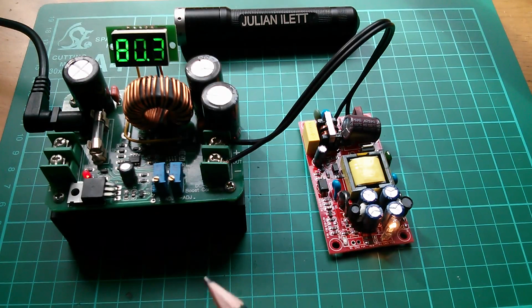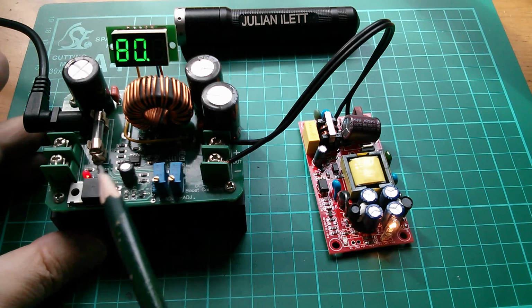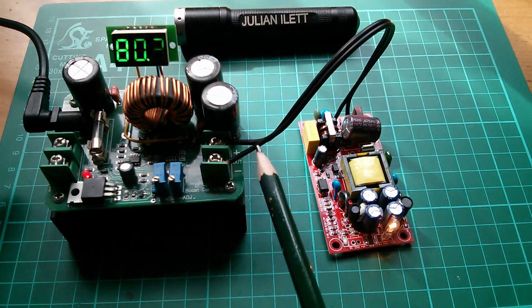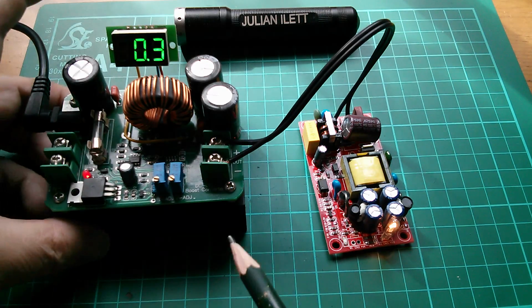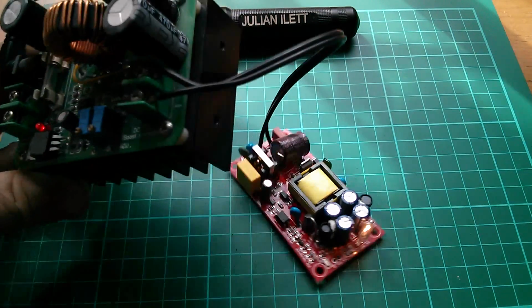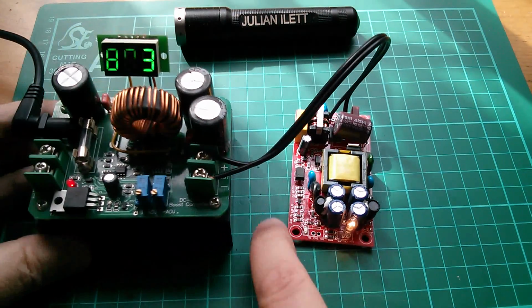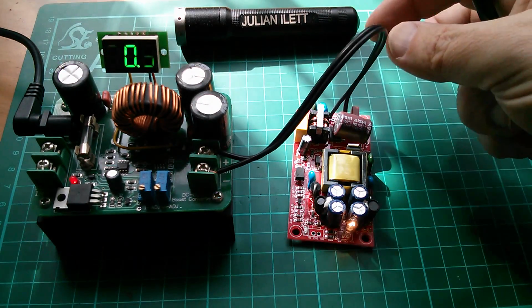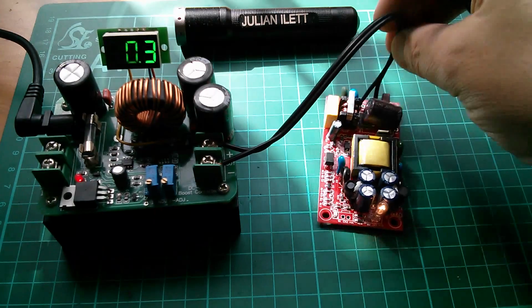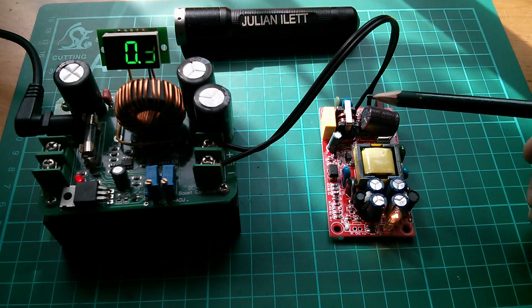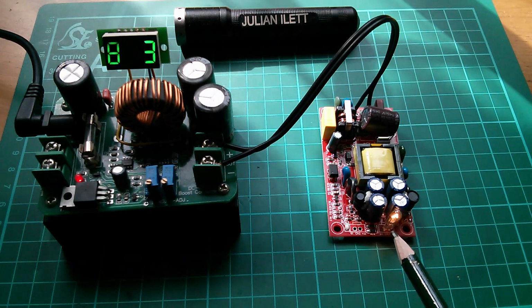So is this a viable system? This boost converter sat in a weatherproof box halfway down the garden next to that 12 volt battery, boosting the voltage up to 80 volts, or maybe even a bit beyond. Let's just check those capacitors. Yeah, they're 470 at 100 volts, so maybe you can get more out of this. Turning the voltage into 80 volts, that running down a very long length of fairly thin wire, and then a power supply at the other end, DC on the input, not AC, bringing that back down to a useful 12 volts and 5 volts for use in my projects.